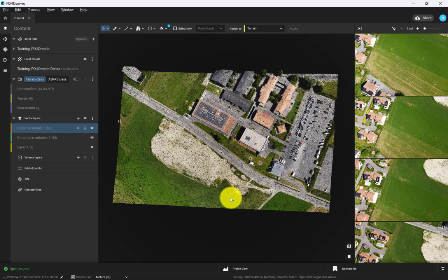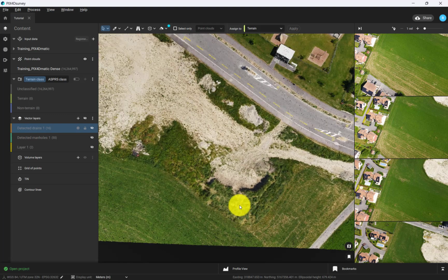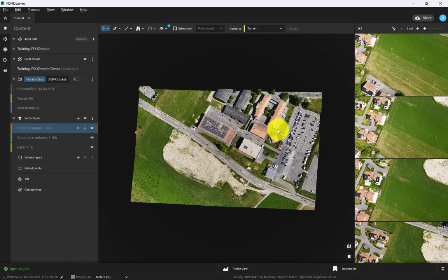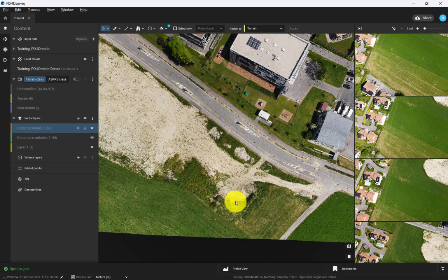Center the interface by looking straight down on the feature or stockpile you want to calculate. When outlining a feature of interest, a top-down view will provide an easier way to verify that you have included all of the stockpile or feature of interest. To ensure that you are looking straight down on the project, tap 7 on your keyboard, which will return you to the default top view.